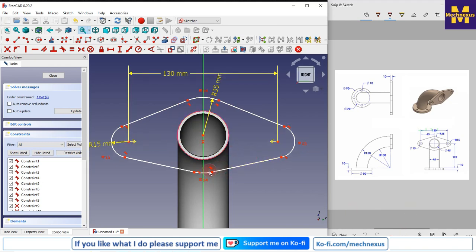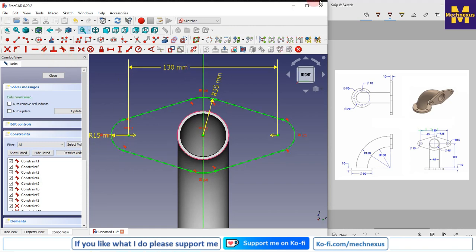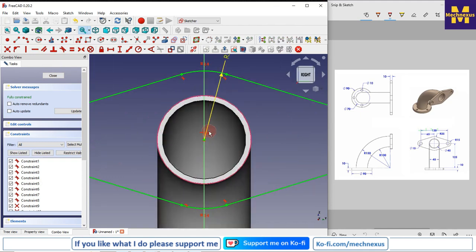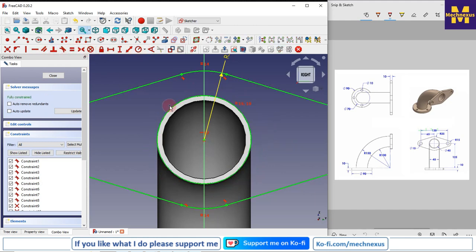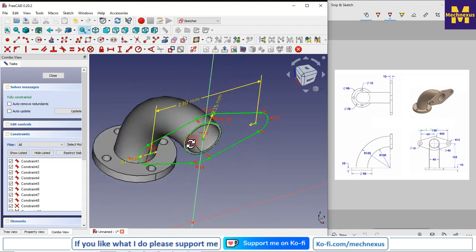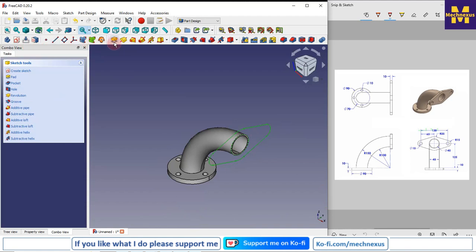Now the thing here, if we move that, this should be horizontal. So I will select this point and this point, and I will give the horizontal constraint. So this is fixed, and now I will draw a circle, and I will make it equal with my projected geometry. So I will simply say equal. So this is how our profile has been drawn. Now I will close the sketch and I will go with a pad.